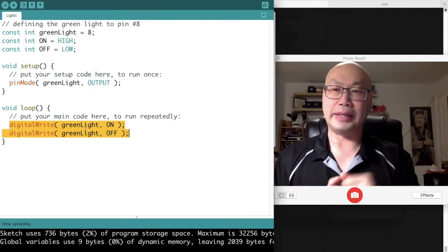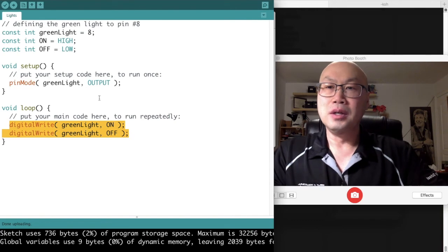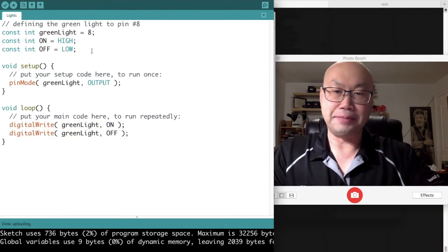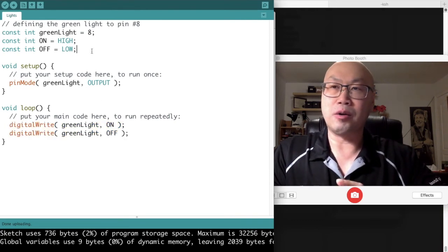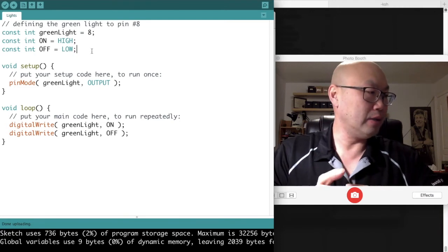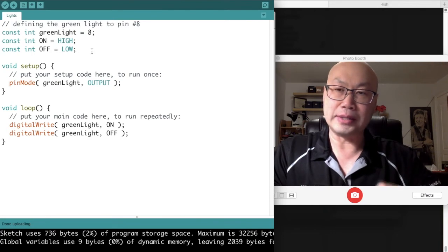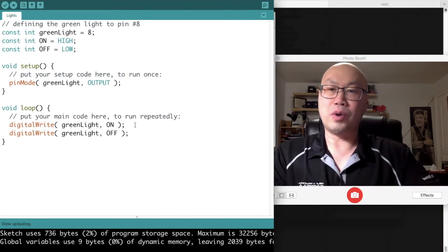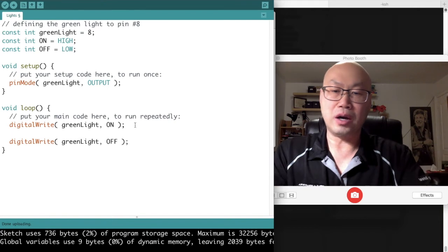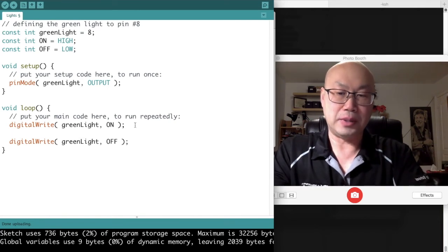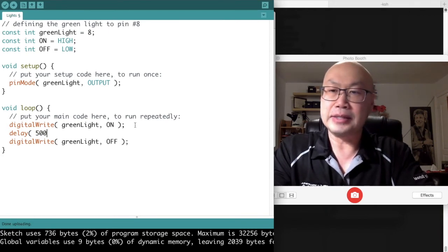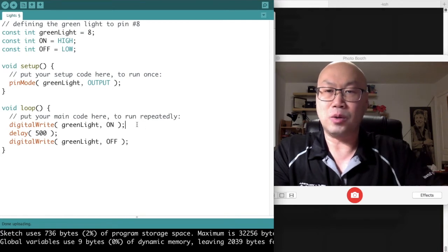How can we get a blinking light? Well, there's a notion of what we call a delay. We could get our program to pause a little bit in between statements. What we really want to do is, after we turn it on, wait a little bit. The command to wait is delay, and what it takes is milliseconds. So maybe I'll comment the code above.